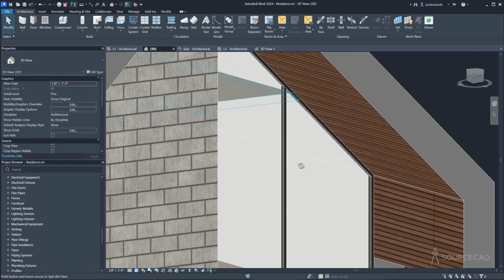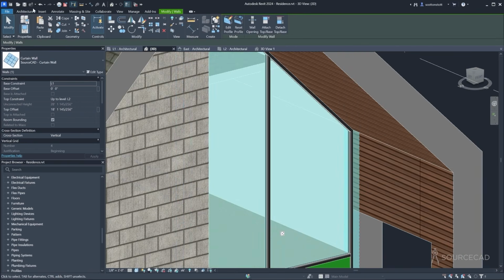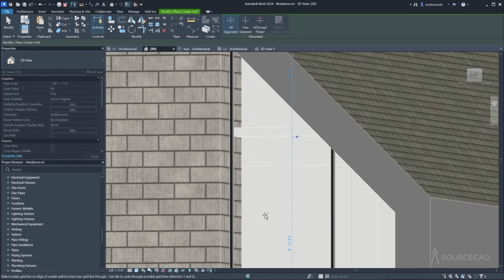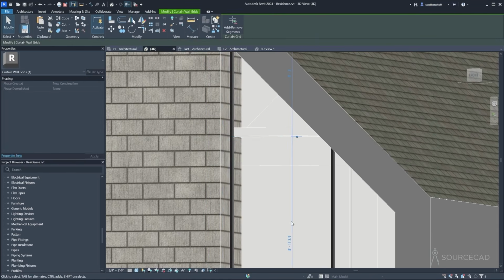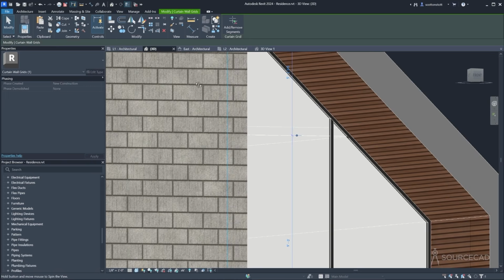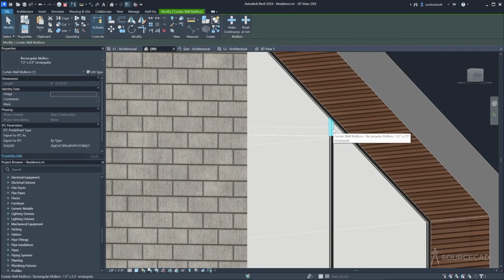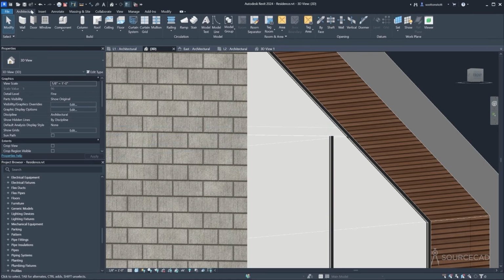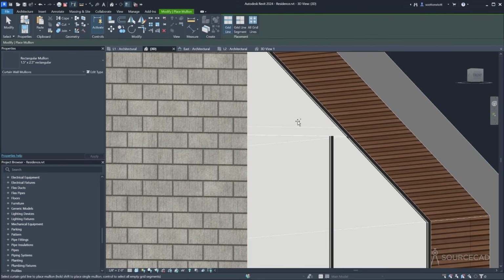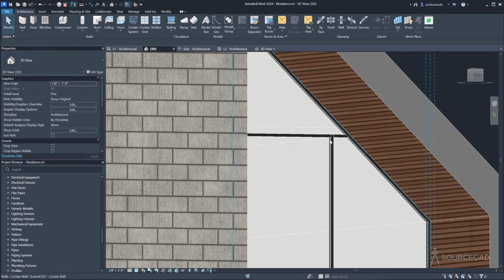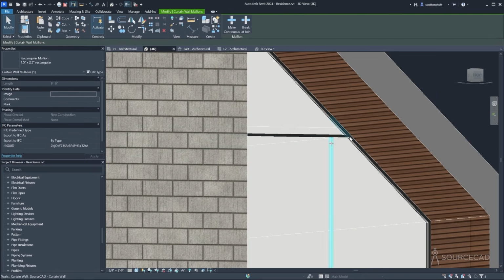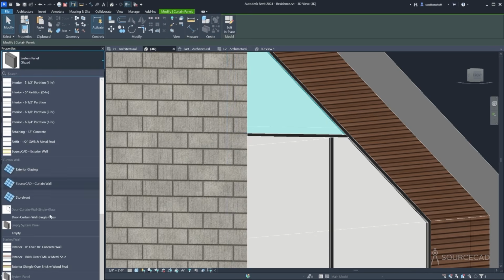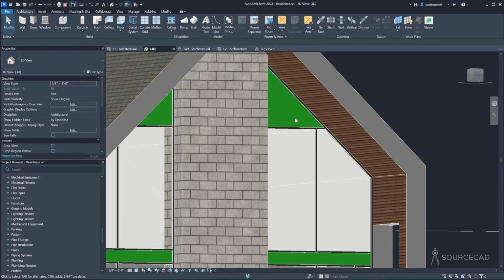We'll do the same thing over here. Select the curtain wall, go to curtain grid, add a curtain grid right about here, select this, change it to exactly 9 feet. Over here, I'm going to get rid of that and remove this little segment, which I don't need, and then add a mullion, just one, on the grid line. And then this vertical mullion should be pulled back. So we have a continuous horizontal one there. And then I will tab select the panel and change its type to solid. All right. So now that makes much more sense on the exterior.